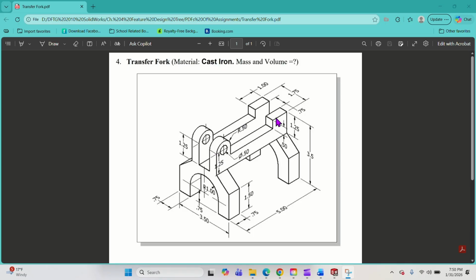Now, these ends are different. One's an arch, one's just flat. And if you look at this center mark right here, it is consistent with the edge that comes at 1 1/4. So that tells me that hole sits at 1 1/4 from the edge right here.